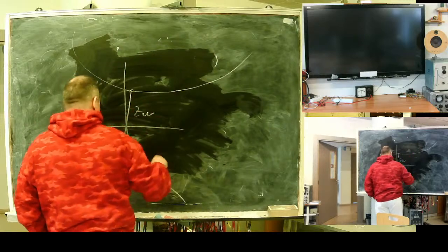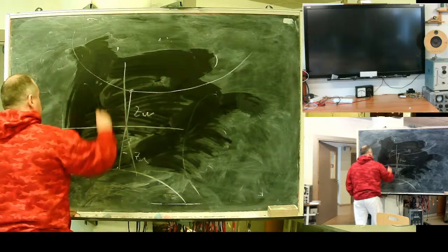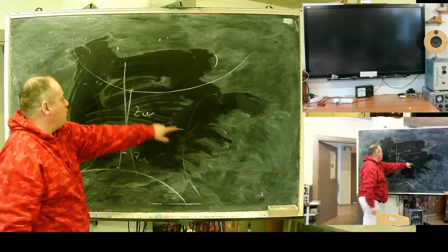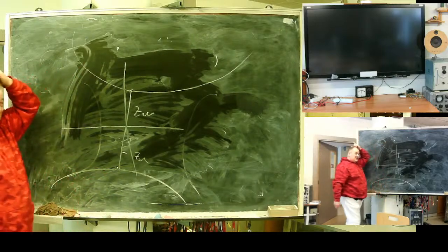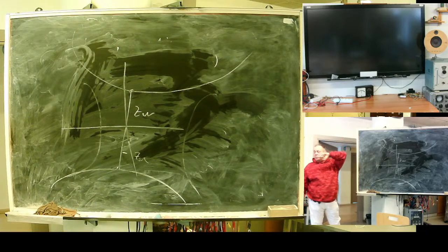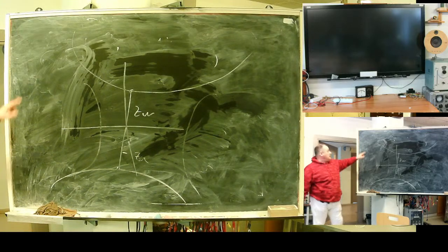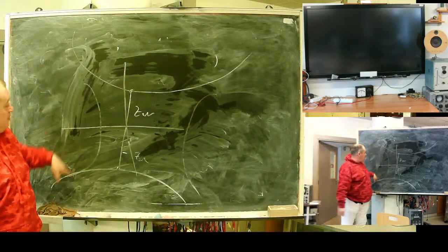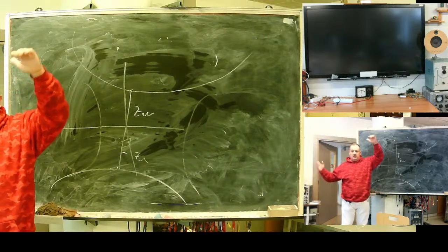They close it as a circle, also like this. So this one is forward, and this one far. When you trace the impedance point during synchronous swings, if they are not going to the full worst case but only swinging, it runs somewhere in kind of circles around the line ends.